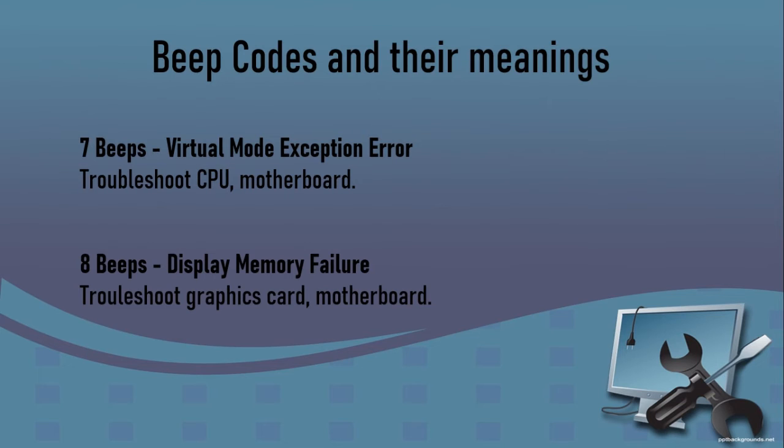8 beeps. Display memory failure. Troubleshoot graphics card in the motherboard. These 8 beeps mean that the BIOS is unable to write to the frame buffer memory on the video card. This means nagmamalfunction ang video card at graphics card natin. So it is recommended to troubleshoot the graphics card in the motherboard.